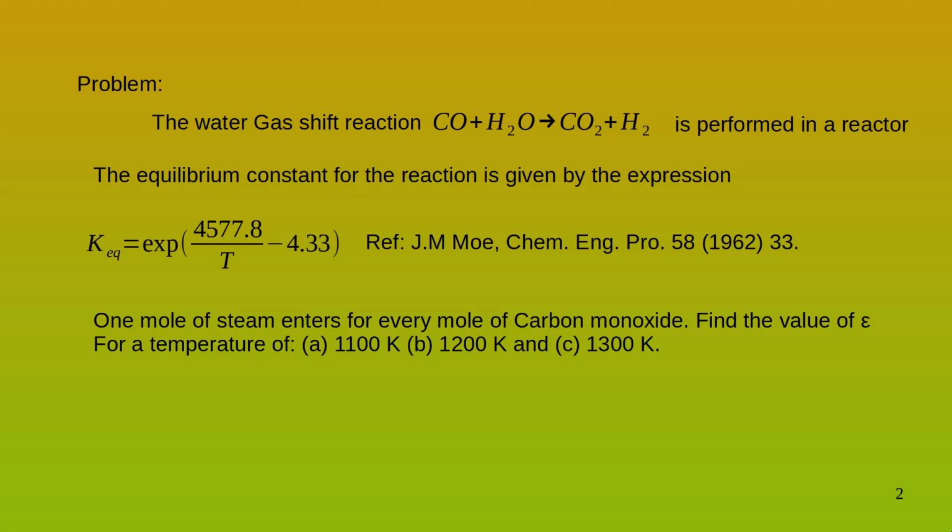K. And then what happens also is the tendency that we calculate the value of heat of reaction at 298 and use the expression where K is directly proportional to the heat of reaction, which is a constant, and inversely proportional to the temperature, and integrate and use this expression for any and every temperature. This itself is pretty erroneous because the heat of reaction does change with temperature.